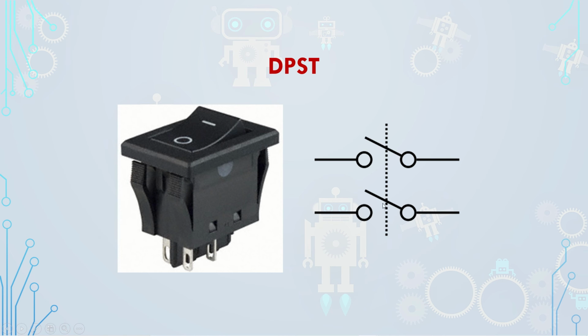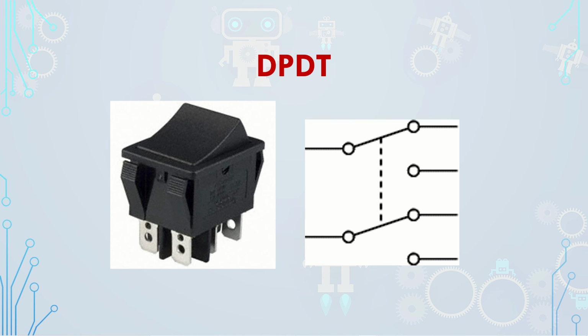These two poles are connected mechanically. This dotted line indicates that they are connected mechanically. It means that if you press this switch, both the switches will move simultaneously when connected to this terminal, and when you release it, both will disconnect. That is called DPST, double pole single throw.